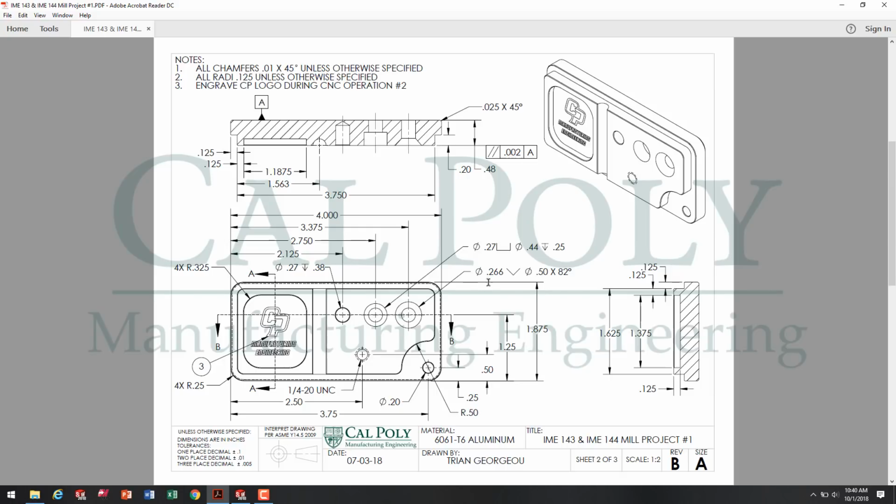We're actually going to make it with the same drill that this one was made with. This is a mistake on the drawing. So we're going to create it with an F-size drill, and the countersink's diameter is going to be 0.5 in diameter by 82 degrees.